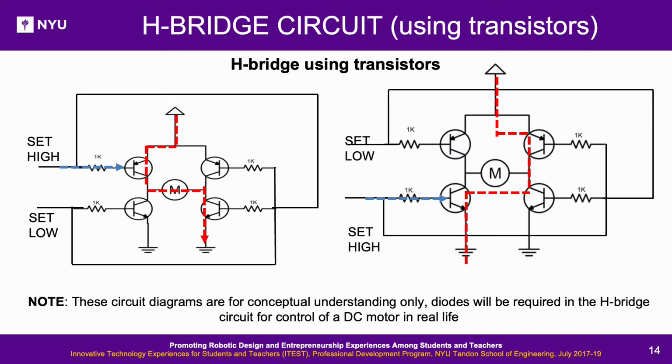H-bridge circuit using transistors. Consider the circuit shown with switches replaced by transistors for electrical switching. The working remains the same. Note: these circuit diagrams are for conceptual understanding only. Diodes will be required in the H-bridge circuit for control of a DC motor in real life.